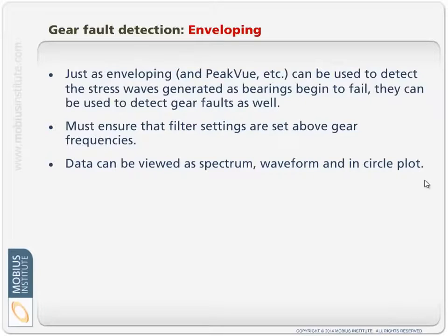In the normal spectrum it's kind of being swamped out because there are all other higher sources of vibration. It's a very short event. It may not be picked up very well in the FFT. There's a lot of issues there. But because we see that as a spike which causes excitation in the higher frequencies, we're exciting higher frequency natural frequencies in the structure or in the sensor itself, we can use a demodulation technique, whether it's peak view or shock pulse or whatever.